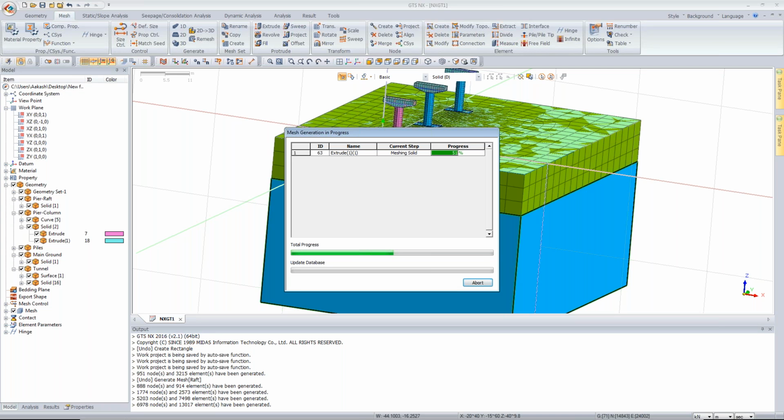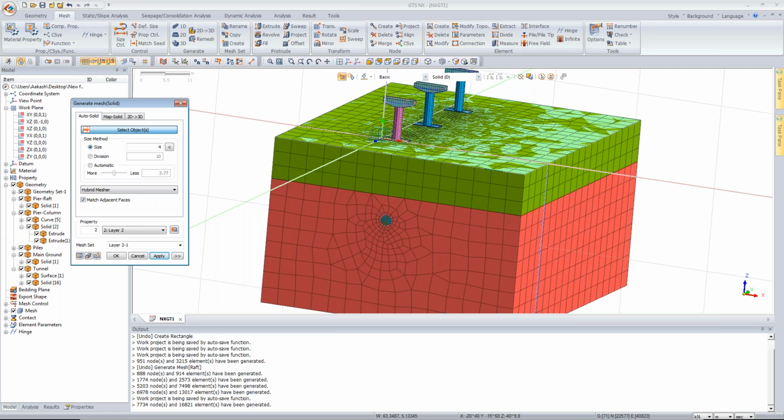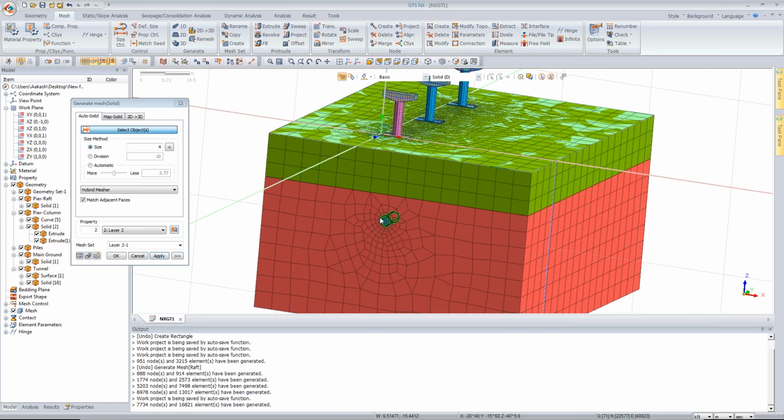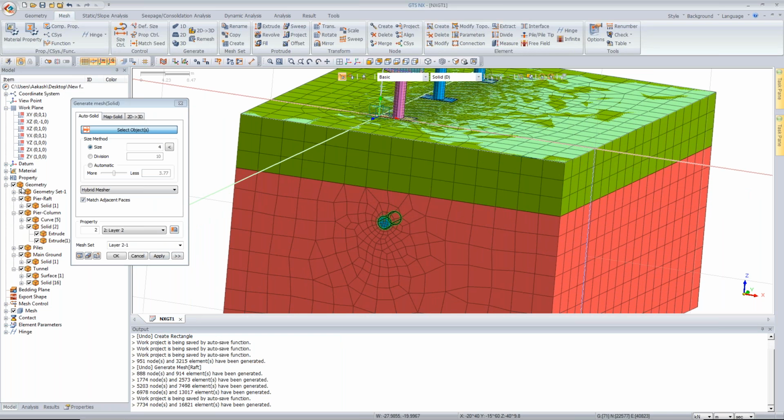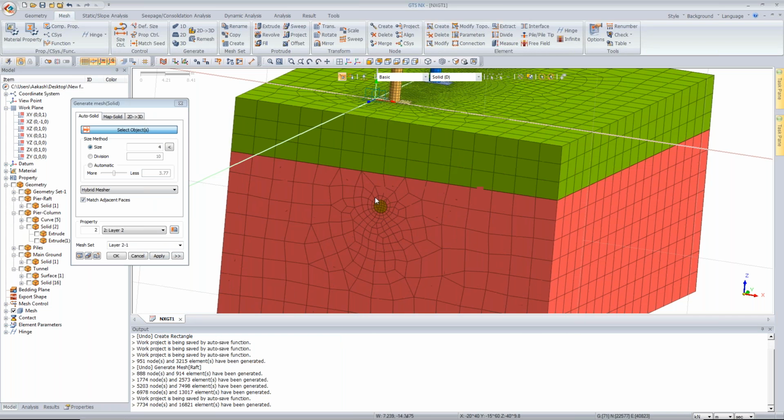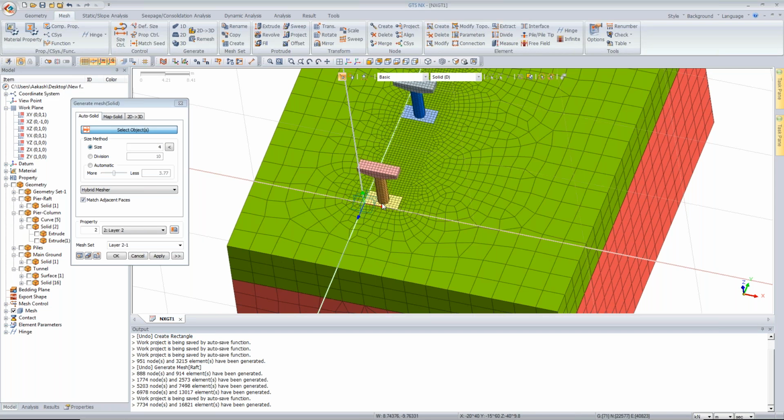Okay, so there you will find a finer mesh, of course. The program takes care of that, but you must make sure that the check duplicate or the auto connect, basically the orange face, exists between the solids before you move on to this phase. Fine. So if I just zoom in, I'm hiding all the geometry. So you can say that the node to node connection has been taken care of by the program. Fine.